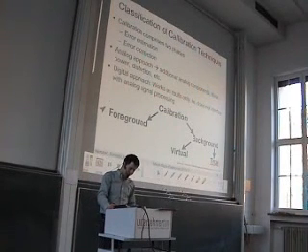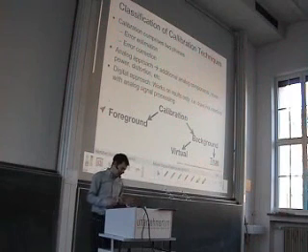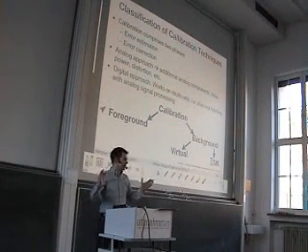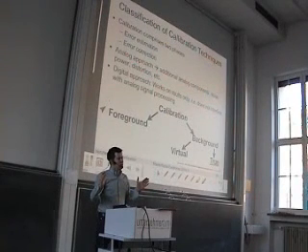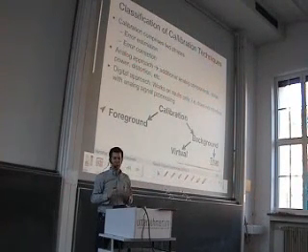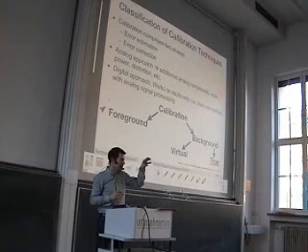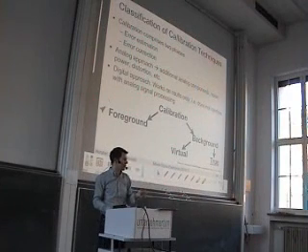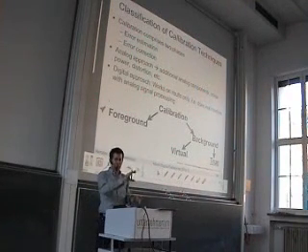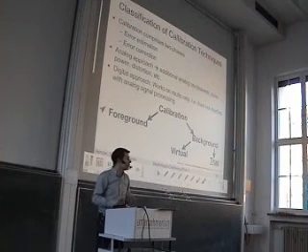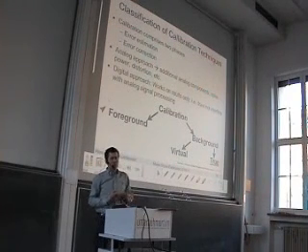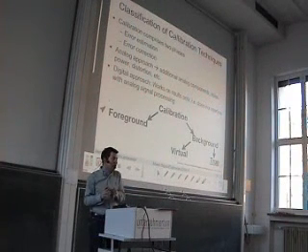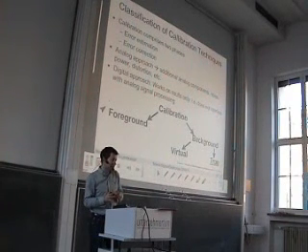There is also a virtual background calibration, and this can be in the context of the pipeline ADC, for instance, where you say I have n pipeline stages and I implement n+1. And I always take one offline, calibrate it, and after it is calibrated, I place it into the signal path again, take another one offline, and calibrate this one. Here you can see, well, this requires additional circuit elements because I need one extra pipeline stage, yes?